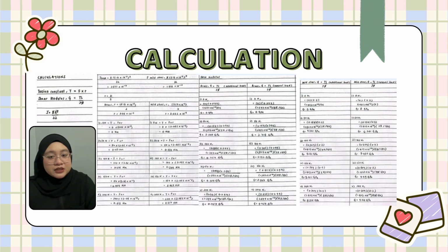Using the experimental data, the value of J is first calculated. Number 2, the applied torque T is substituted into the shear stress equation. Number 3, the maximum shear stress is determined at the outer radius. Number 4, the modulus of rigidity G is calculated by rearranging the angle of twist equation.